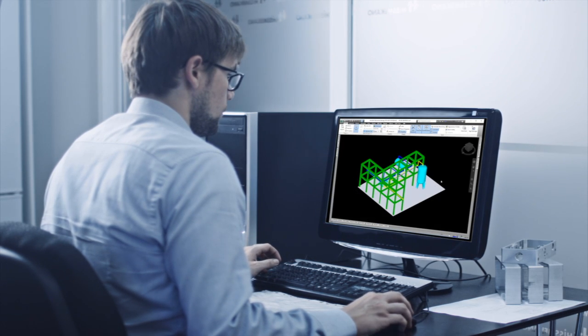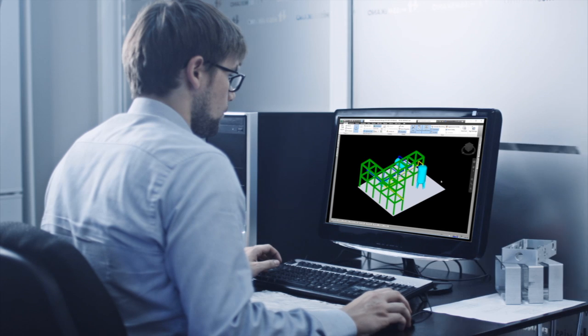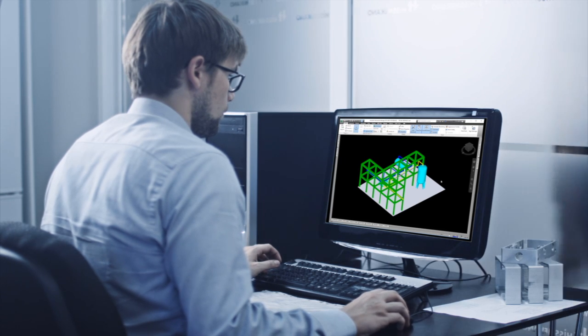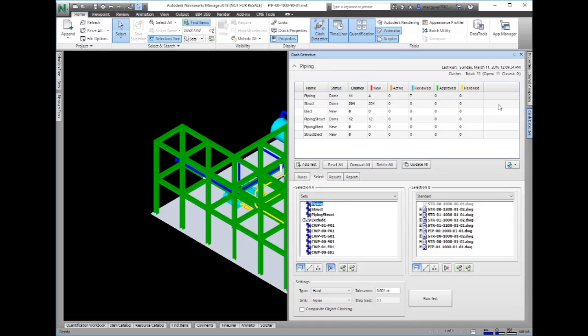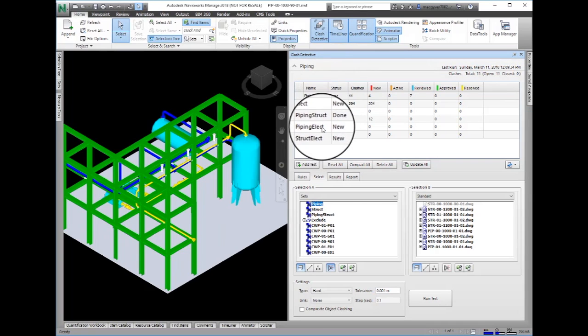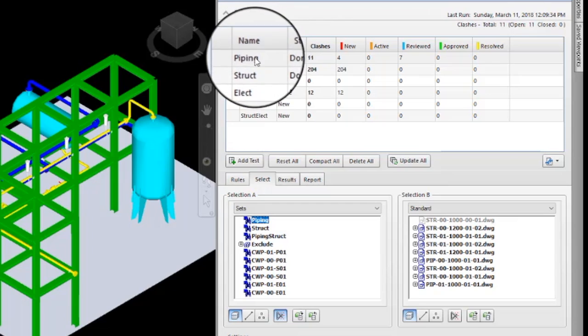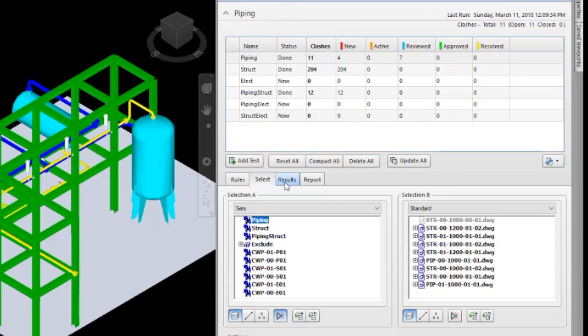This program will allow you to view your Navisworks clashes inside other Autodesk products such as AutoCAD. Let's have a look at how to create your configuration. First, we open the Clash Detective. As you can see on this table, we have some Clash tests already defined. We will be basing our configuration off of those clashes.